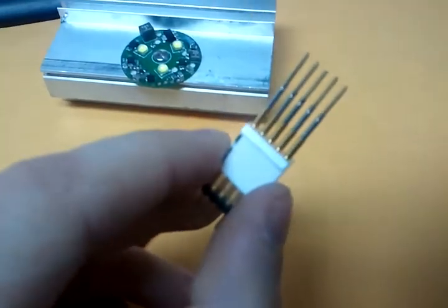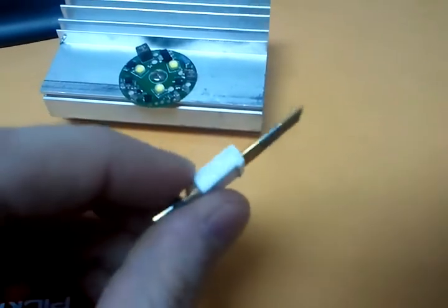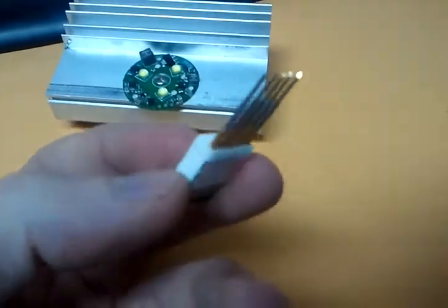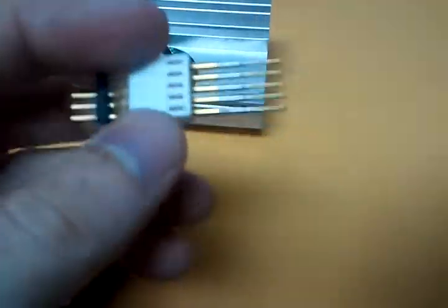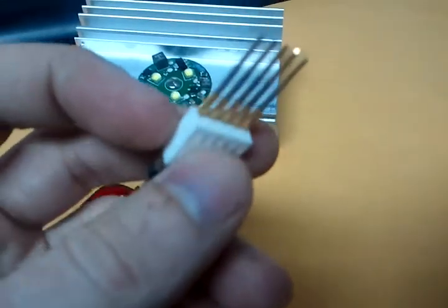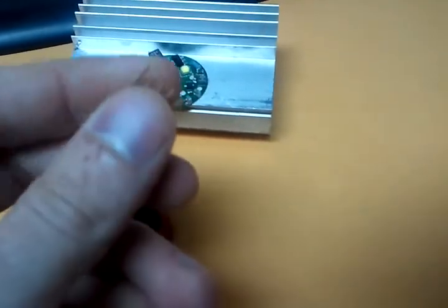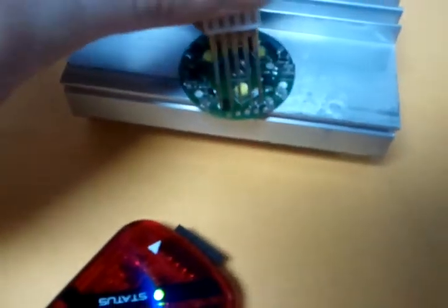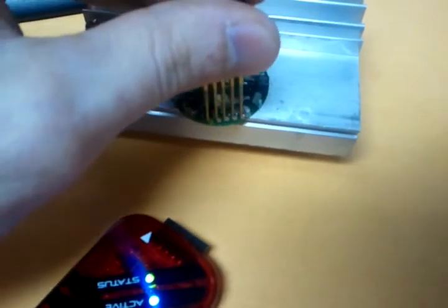You can get these pogo pins at any electronic supplier, and this is just a random connector housing that I had laying around. You can use anything you want, but it just happened to be the right pitch to shove the pins through, and it holds them in a nice position where they don't easily misalign. But the idea is just to be able to get these pogo pins to press down on the programming pads.